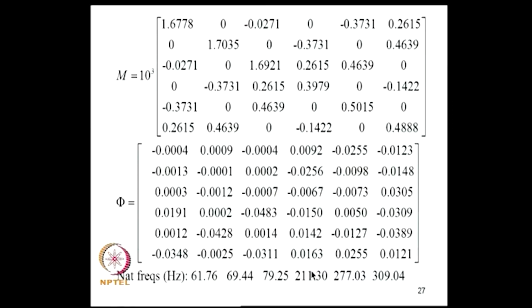So, this at least completes the free vibration problem, and subsequently if there are any forces acting on the structure and if you have information about damping in the elements etc., you could formulate the damping matrix, you can formulate the force vector, and the complete equilibrium equation for force response analysis would subsequently be ready.